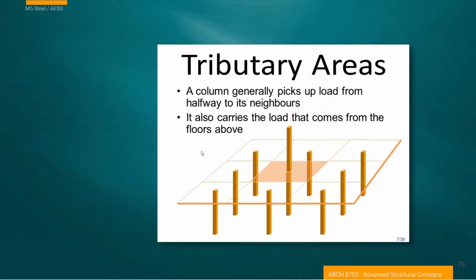And one of the things we commonly do as architects, in at least our initial structural analysis, is to look at how loads are carried from our roof and floor systems and our wall systems down into our foundation systems. And we're really basically talking about gravity loads at this point, not seismic loads or wind loads, because those would be lateral, at least in the case of wind load.